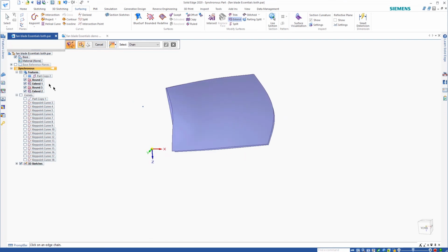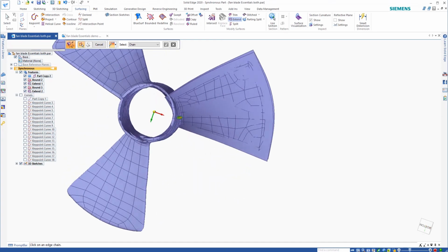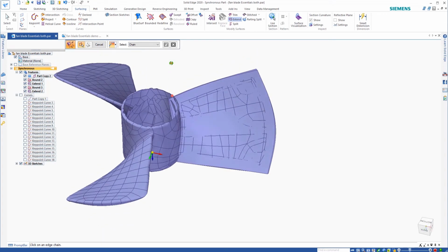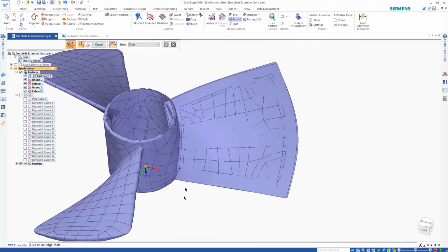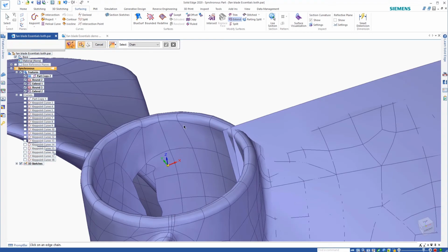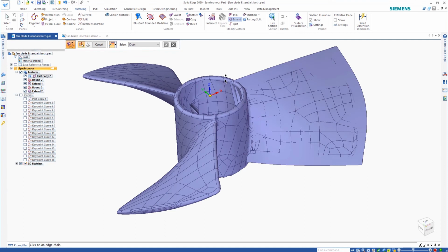So what we're going to do now is, if you look at the part here, the main auto surface, you see that I'm just going to model a blade shape from the top down and then replace the face of the top and bottom of that extrusion. So in order to do that, I'll just go ahead and sketch on this top plane here, because this is already aligned to the world coming from Essentials.